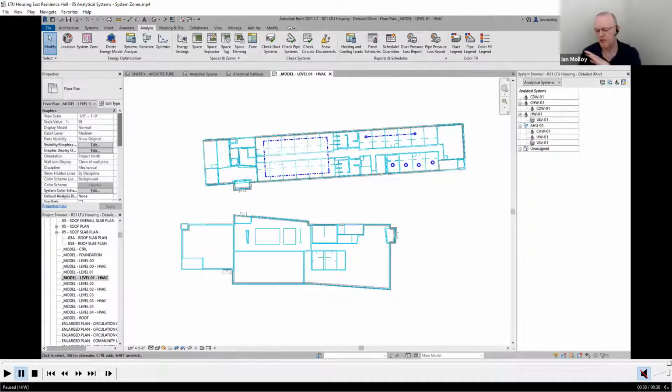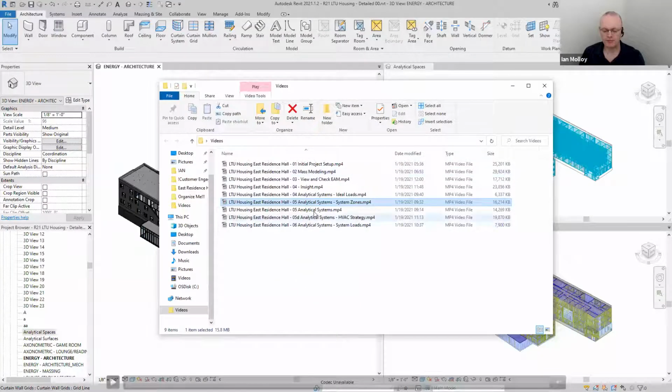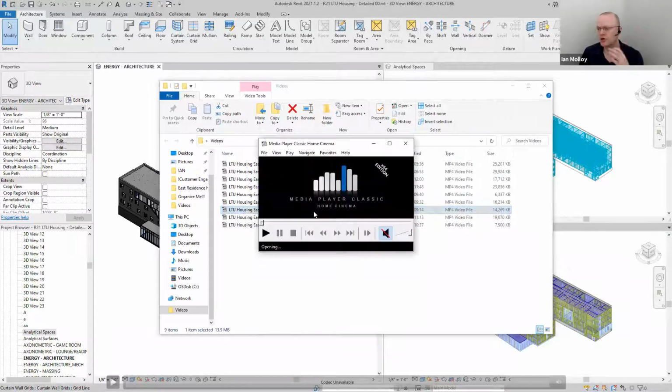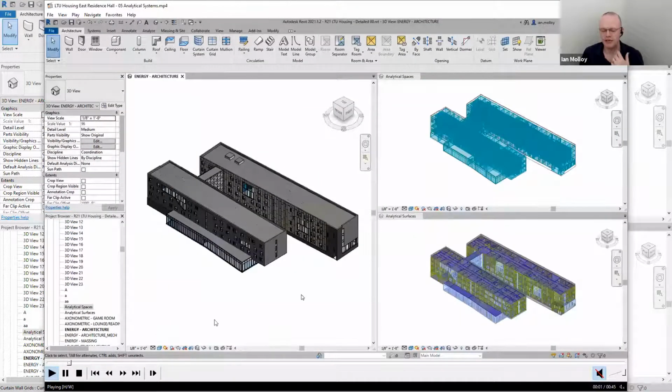And so again, you can be as broad brush about it as you want, like, hey, just draw a box around the whole thing and say all spaces have their own VAV. Or you can say there's a north, south, east, west zone and things like that, right? So it allows you to capture that initial overall system topology. And it's basically here using the Energy Plus schema. All the objects that you see in Energy Plus and OpenStudio schema are essentially what's represented here.